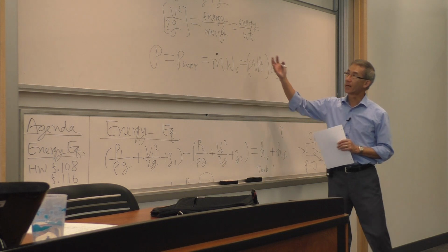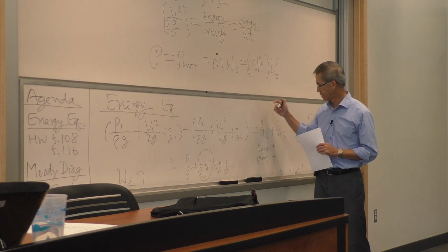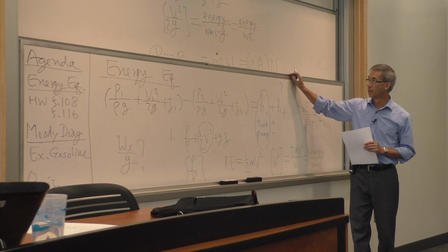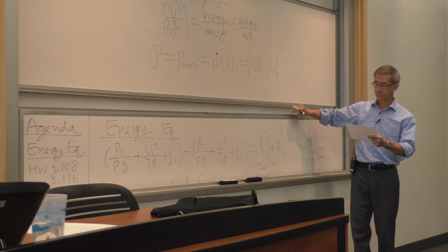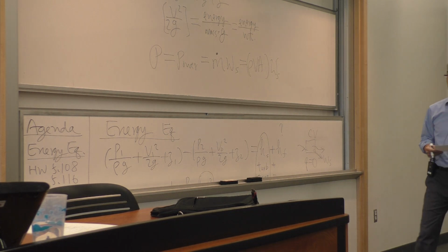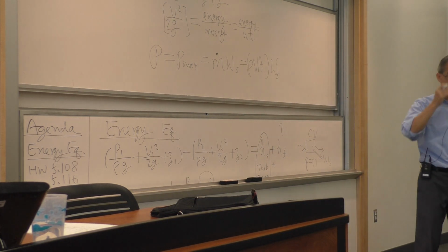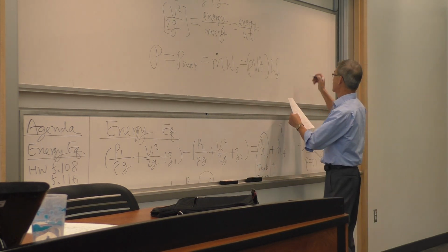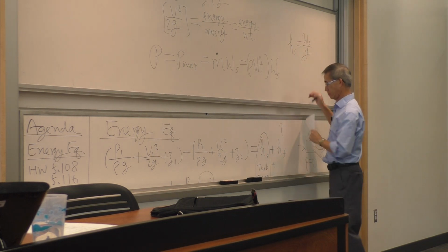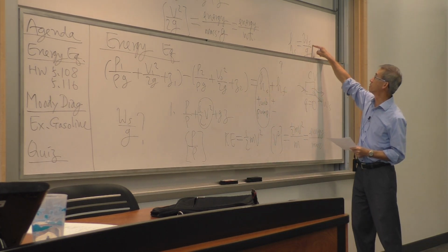So what all this ties into is, given the head rise due to a fluid machine, a pump or turbine, this x of s, we can tie that to the power through this equation of m dot, the mass flow rate, times the specific work, where the specific work in what we have seen is given here by this equation.